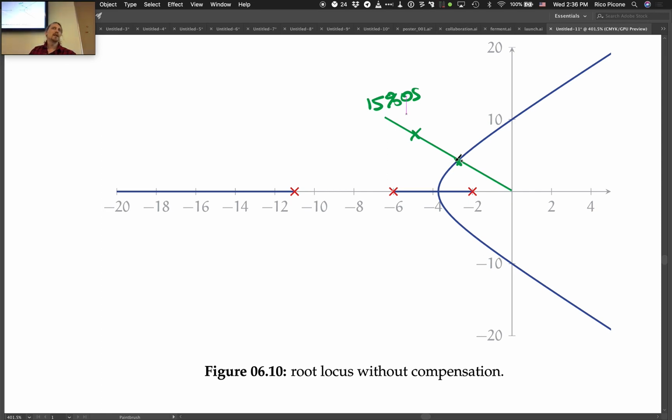15.8. Usually, I did show you the idiom to add in more gain values if you want, but oftentimes, especially if you're going to add a compensator in there, it's probably not a big deal. Just be close. And then when you add the derivative compensator in there, you're going to adjust again anyways. So I wouldn't obsess, especially about the first gain you choose. The next gain can make up for it.